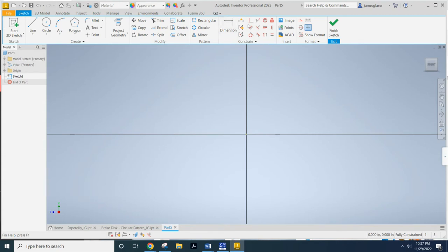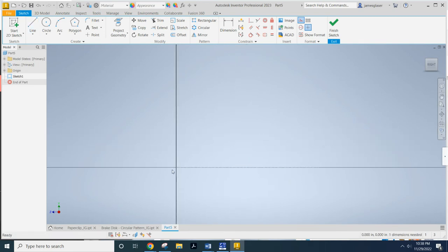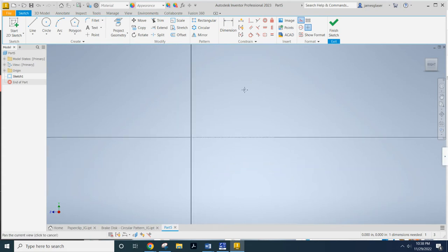So what I'm going to do first is create a plane for us to actually work off of. I'm going to make a construction line, locking in with the origin and just dragging that out a little ways, so that I have some geometry to play with. From the dimensions that I've got, the thing is an inch wide. So just dragging out that construction line to be an inch wide will work just fine for us.